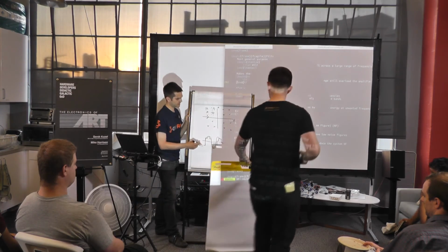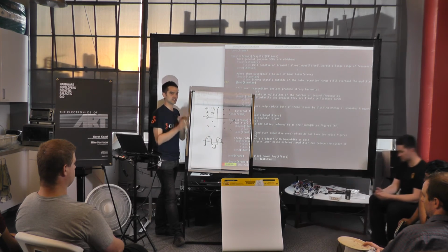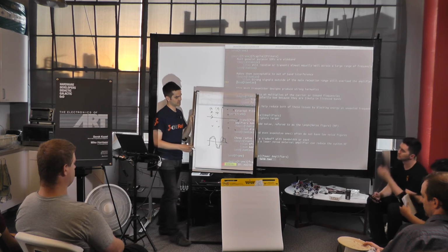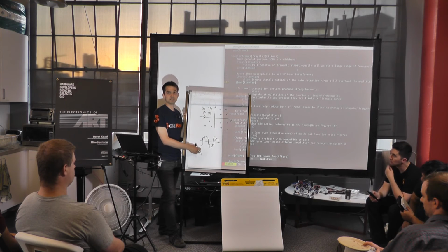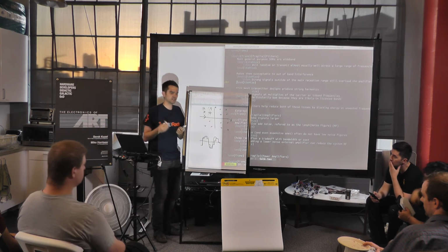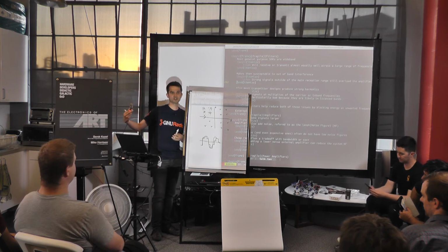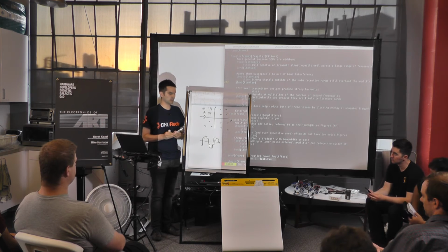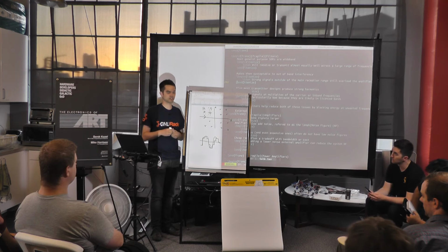And that ends up contributing to the system noise, because these transitions are very, very high frequency, and you start doing the math, and you end up with a bunch more system noise in there. And so that degrades the quality of the signal that you're receiving. So you want to have as many bits as possible. This little cheap receiver has 8 bits. So you only get 256 levels of signal there. The slightly larger brother has a 12-bit ADC, and it's sampling much more quickly, and it's actually doing decimation, so you get 13 bits or so of information.